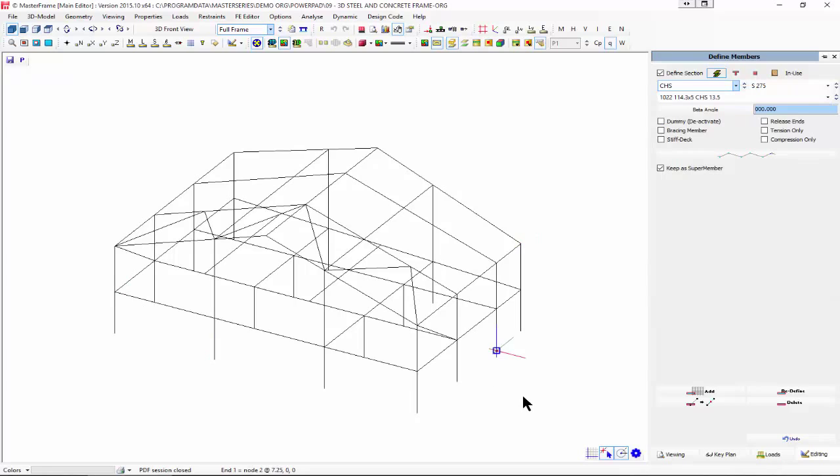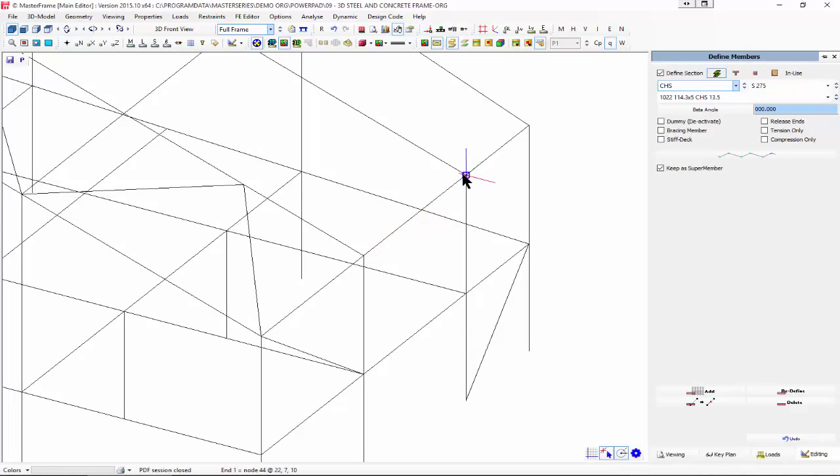And I can then swing around here and put in some bracing between that node and that node. Very simple. And then I could put this opposite coming in there. I can also, while I'm doing that, do advanced things like saying, well, actually, I should release the ends, and it is a tension only member.